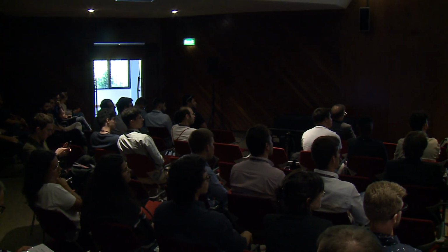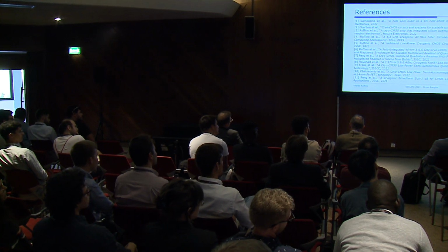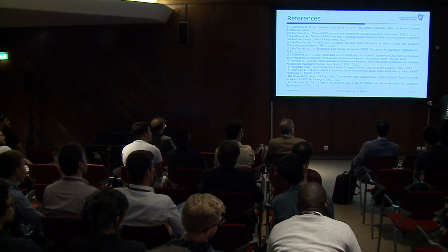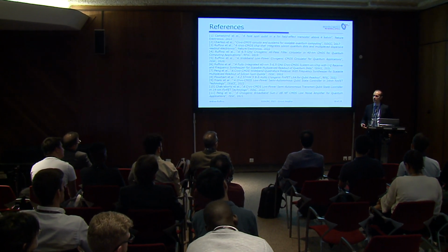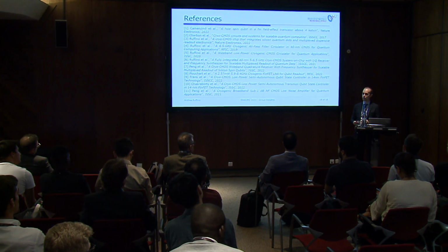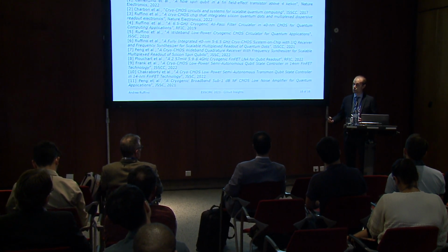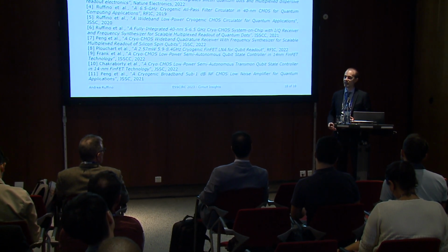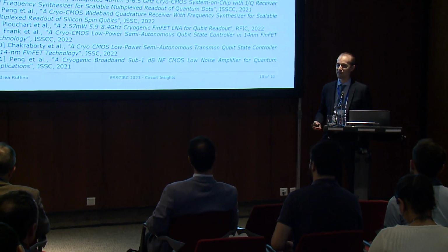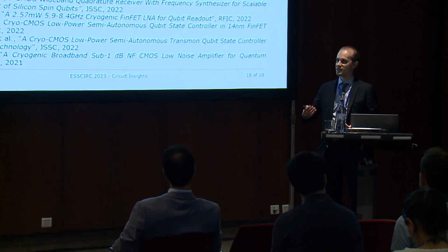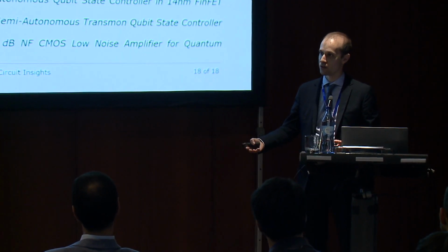Okay, thank you very much for the question. I think this hits very close to home, especially on the device side, because I was involved in the early research developments of cryogenic CMOS circuits, and the way we designed the first circuits was basically by using room temperature models for the simulation, and then exploiting the circuit intuitions to know as a circuit designer what will change when designing your cryogenic CMOS circuits.